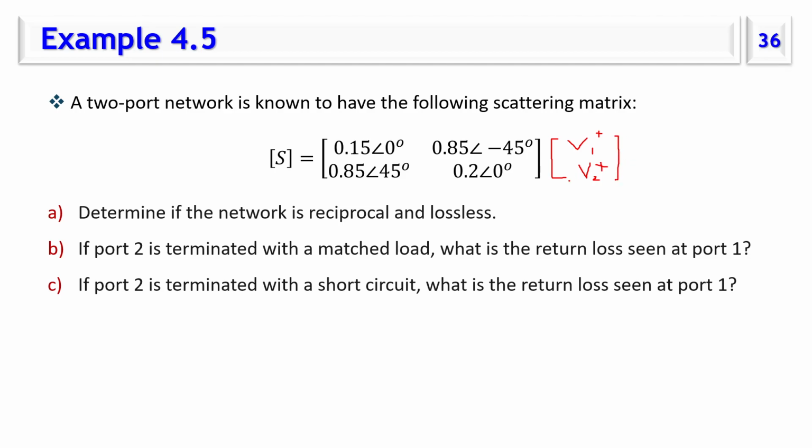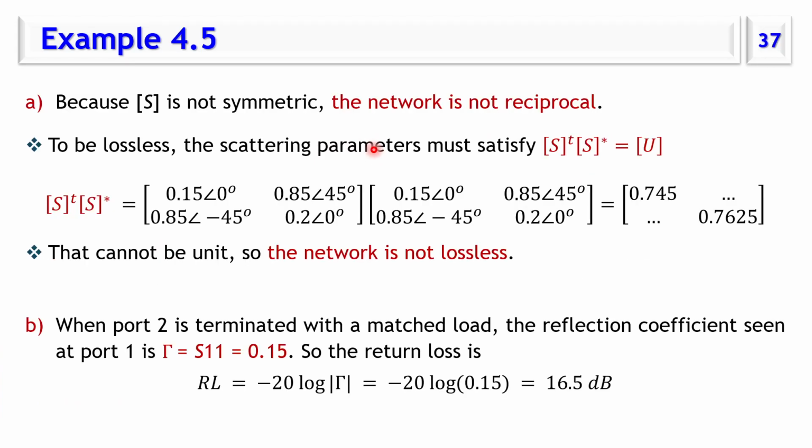This will equal 0. So in this case, S11 will equal 0.15, and what is requested is the return loss. So the return loss is minus 20 log of S11 in this case, which is 16.5 dB.